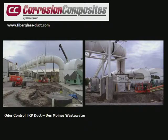And the reason for that is the bridge designer designed the bridge, and our consultant did the calculations for the duct, and the duct turned out stiffer and stronger than the bridge. So it was decided that one had to give, so the bridge was allowed to support our duct only by having flex connectors every 20 feet.